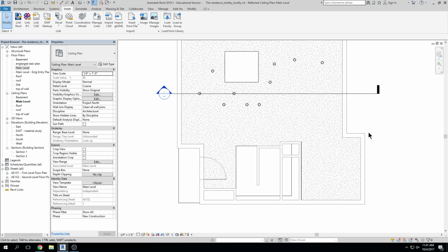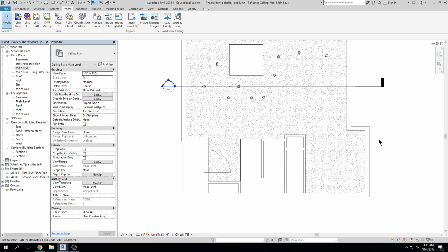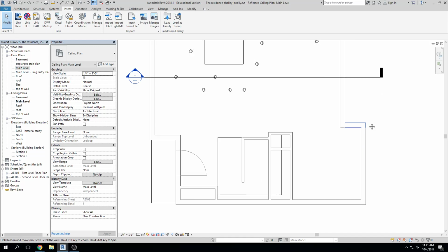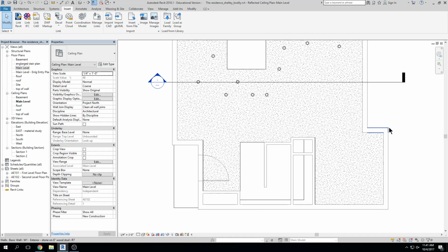And the way that we're going to do this is that essentially we have to draw a wall off of the ceiling, right? And then we have to create a ceiling below the level of the existing level of the ceiling, okay? It's not super easy. There's not a soffit tool. It's not an easy process, and you have to switch from plan view, RCP view, to a sectional view to make sure you get it right, okay?